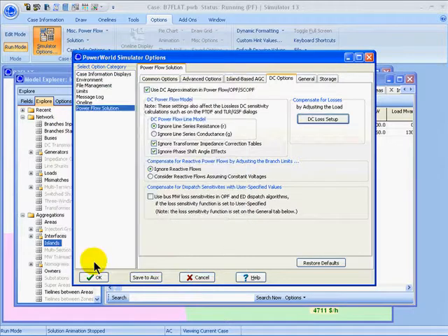Simulator also allows you to automatically have the line ratings, the line limits, derated in order to adjust for the fact that there aren't any reactive power flowing on the lines. And the default option is just to ignore the reactive flows. So the limits on the line will basically then apply only to the megawatt flow.